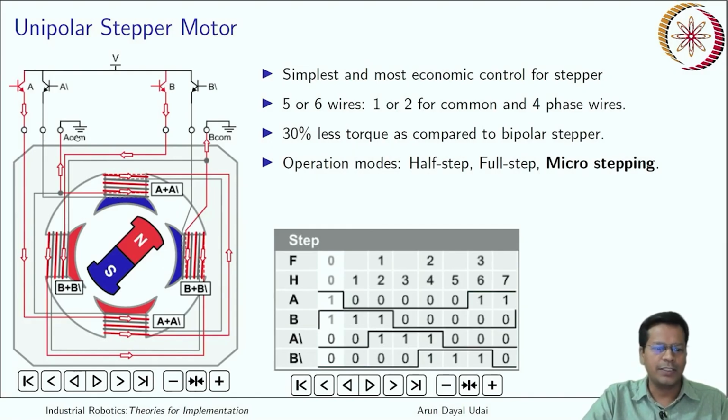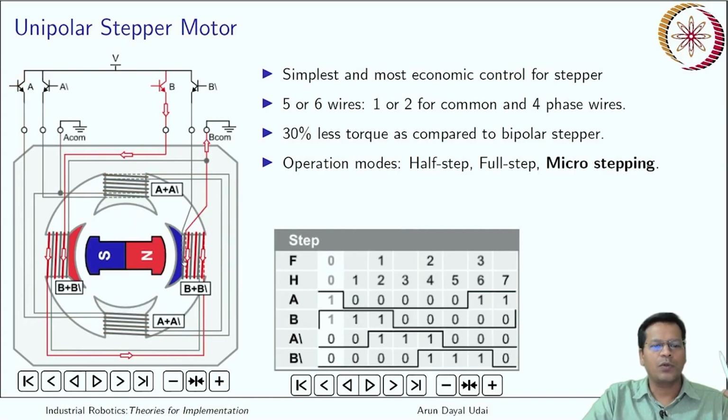So now let us see how it works. Let us say your motor has started already. It is here in this position. What you see, the blue one, is the south pole, which is attracting the north pole of the armature. Armature is at an angle now. So when both the poles are high, the armature goes to this particular position. This is a magnet which gets attracted towards the pole which is high. In the next position you will see, only one of the poles is high, and the other one becomes opposite to that.